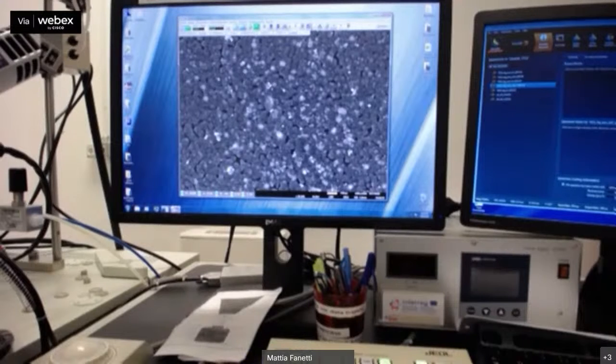So how big are these clusters that I see here? If these are 100 nanometer, these small clusters are, okay, let's use this. So this, for example, this small cluster is 17 nanometer. And there are also smaller clusters. And now we are at 15 kilovolt, not at the highest possible resolution, so we have a resolution, let's say, of a few nanometer. This is, for example, 11 nanometer. Okay, this is what we can see with the secondary.